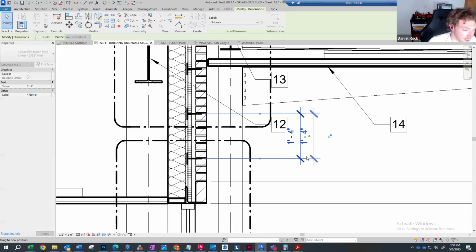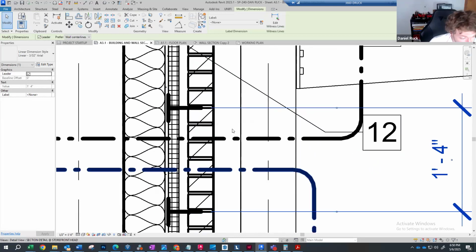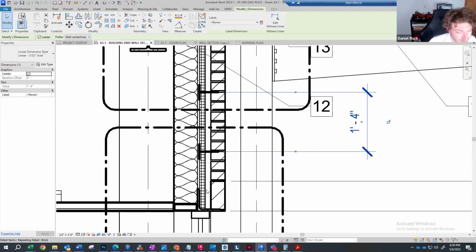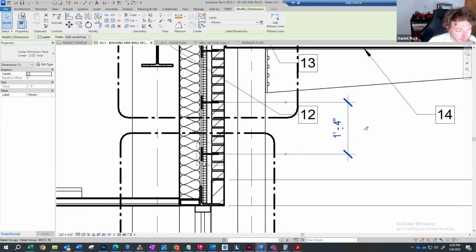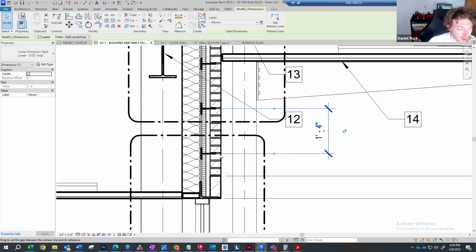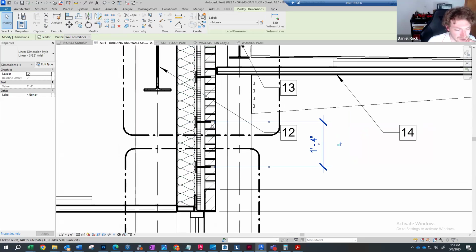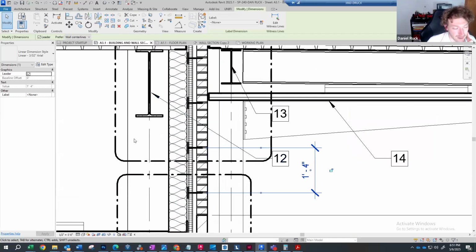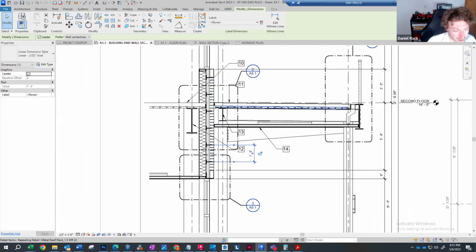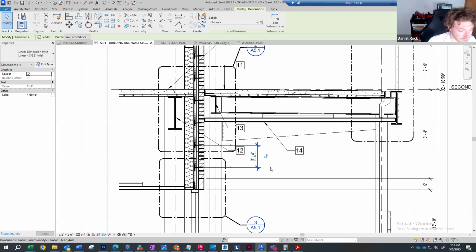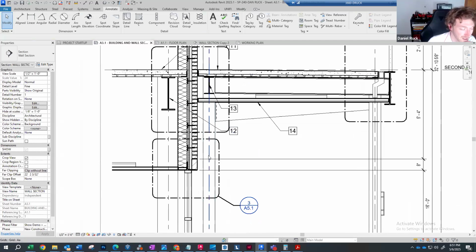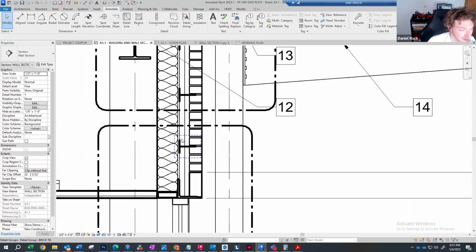Essentially, you stack or lay your brick, and you provide a brick tie that is tied back to the structure of your wall assembly. Then you start to lay brick on top of that. You go up 8 courses, which is 16 inches, and then you lay another row of brick ties. This is tying back your brick facade to the building itself. So when we say masonry ties or brick ties at 16 inches on center, these are the components we are talking about.